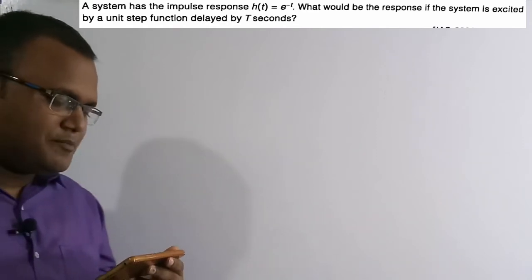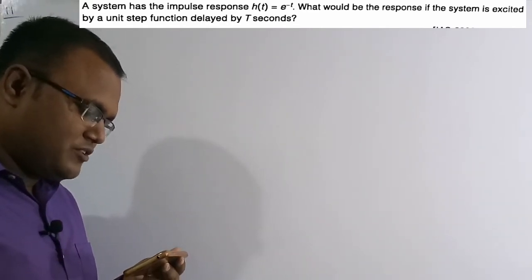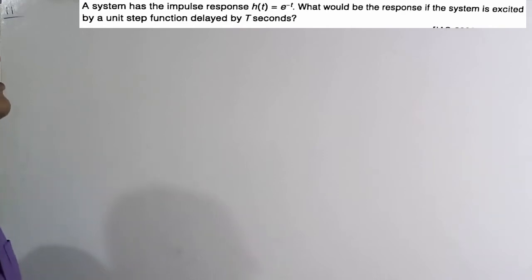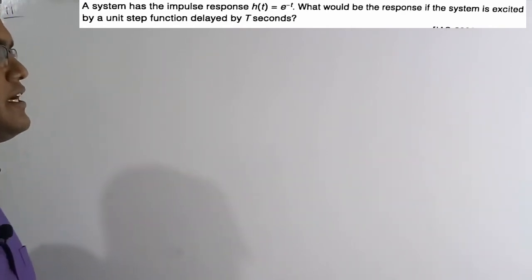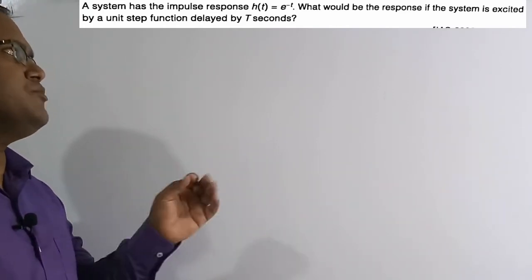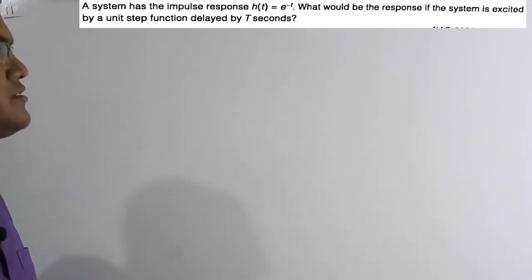So let's get started. Now we are going to solve the 11th question. See the question here. A system has the impulse response h of t is equal to e to the power of minus t. What would be the response if the system is excited by a unit step function delayed by T seconds? In this question they have given the impulse response of an LTI system and also the input as a delayed unit step function by T seconds. We need to find the response of this system, and this question was given in the IAS 2008 for 6 marks.